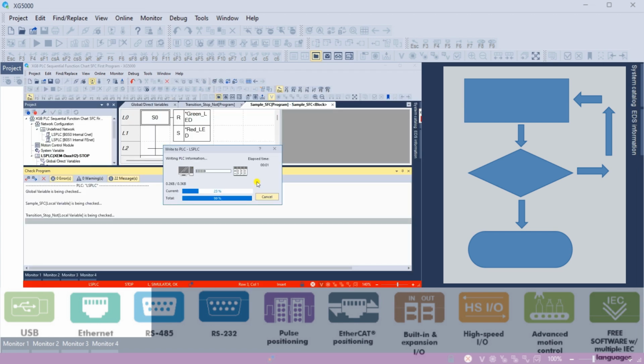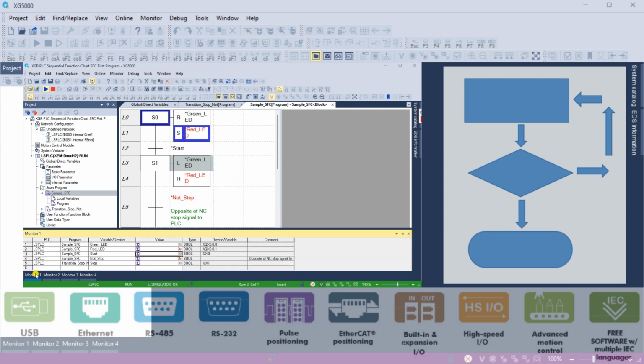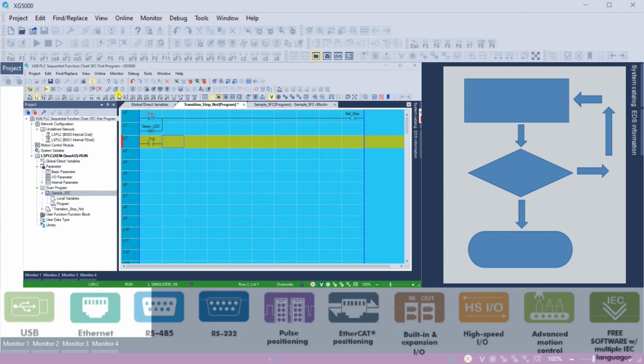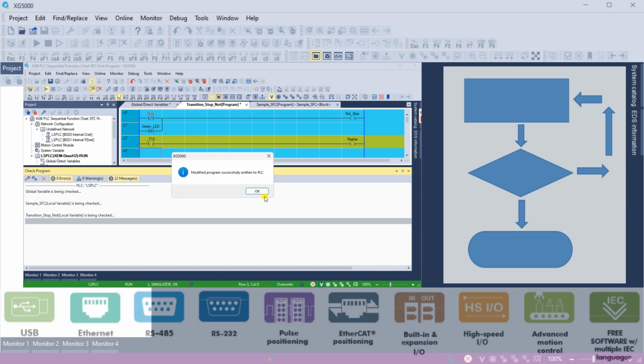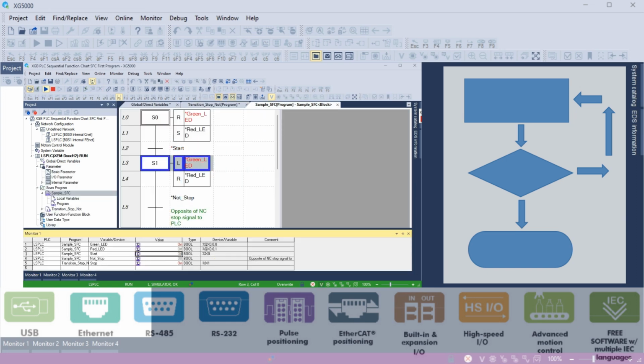This is step 3 of 5 in the program development process. The simulation and monitoring screens will aid you in visualizing and refining your logical sequence of operations, concentrating on one step of your logic at a time. During this session, we will demonstrate how to simulate the start-stop circuit we previously developed in the XG5000 programming software before translating into the actual XGB PLC.